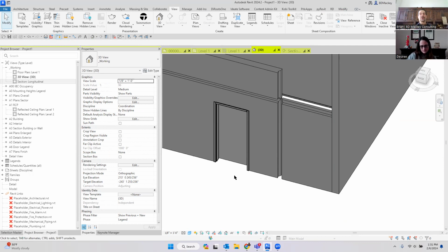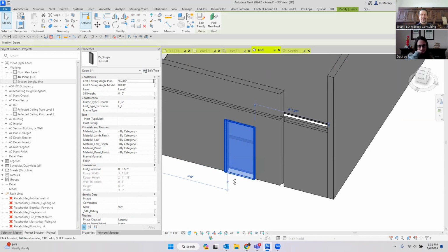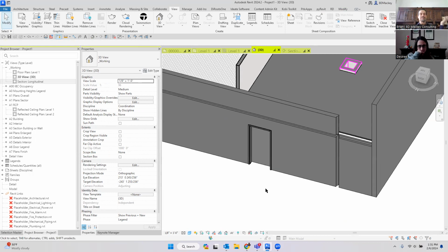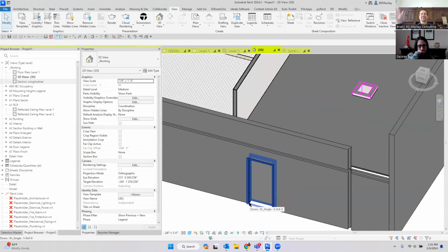She just created parts through the link and then was able to divide them where she thought they should actually be, and she didn't model anything herself. If the architect came in and was like, no, I wanted the door to be over here, her parts updated with where the door got moved to from that link. Downside is when the architect moved it and gave her 6 inches of concrete next to it, she's kind of like, hey guys, you can't do that.